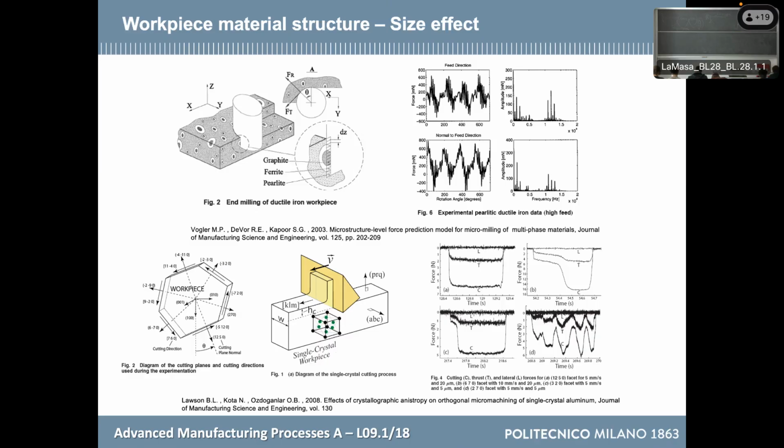But in this case, the interesting fact is that if you put your tool in a different orientation with respect to the material, you are soliciting different ways of deformation of the lattice. Because depending on the type of lattice, the materials can be more or less deformable. For example, magnesium has really a small number of ways you can apply for deforming it, but still, depending on the type of lattice, BCC, for example, or others, can have different ways.